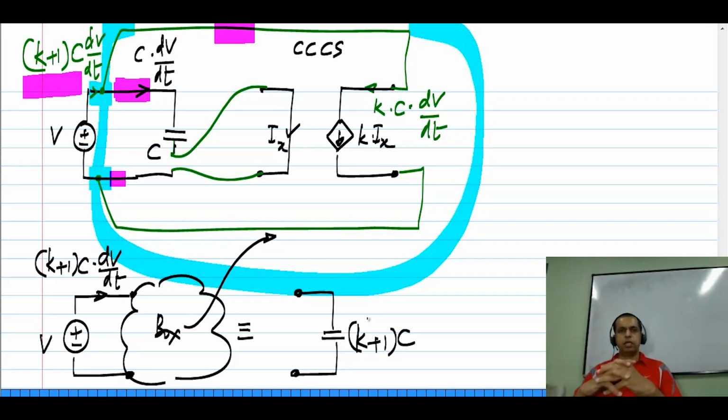So you could have a box with very complicated circuitry here, but let's say across the terminals you measure the voltage and current and come up with a relationship V equals I times something. Now you know that that relationship belongs to a resistor. So this whole entire complicated circuit within the box cannot be distinguished from another box which consists of a single resistor of that value.